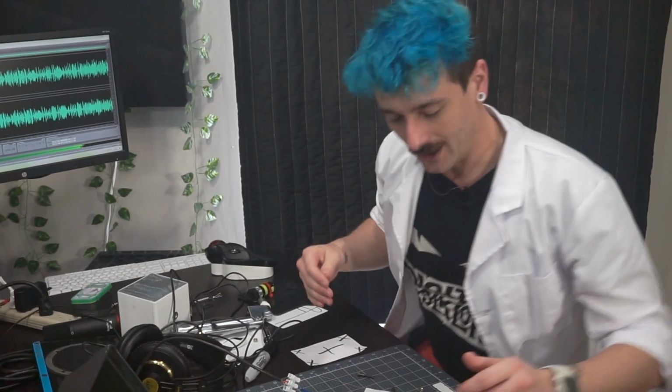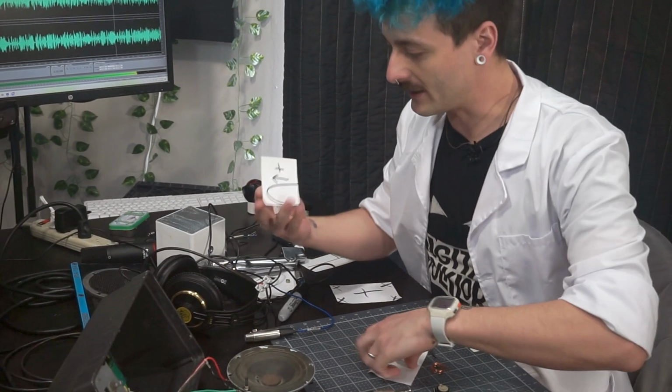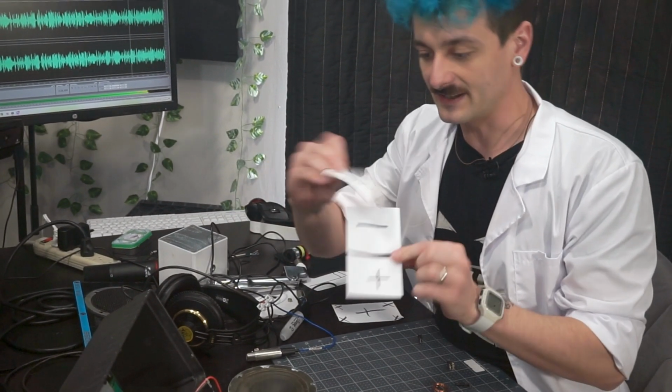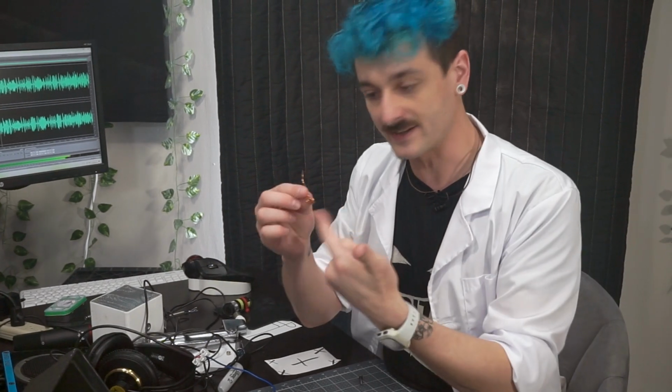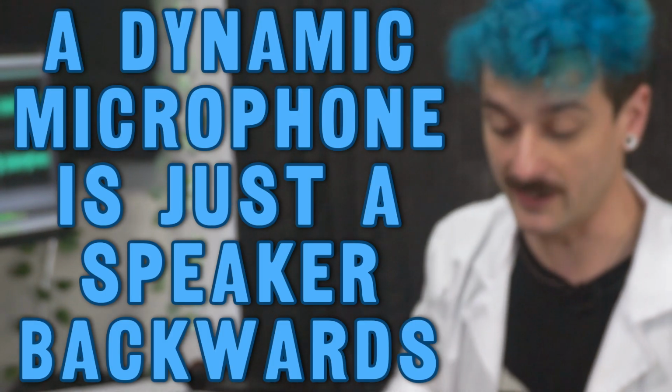Am I good? Okay. There's no fundamental difference between these, and that might seem like magic, but it's literally the same thing we talked about before with the magnets. Instead of the coil wiggling the cone using magnets, you're wiggling that cone with your voice, and that's moving the coil past the magnet, which generates a small electrical signal in the coil, which we can measure. A dynamic microphone is just a speaker backwards. That's what a dynamic microphone is.